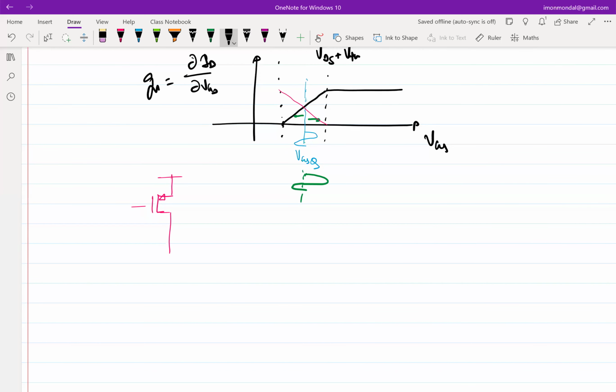And if I sum up the currents, which is normally pretty easily done, summing currents in analog circuits is probably one of the easiest things. You just connect the two terminals and ensure that they are not subtracted. You can both subtract or add, but fortunately, in the case of PMOS and NMOS, they both add up if you connect it like this. So if you do this, you should be able to get a fairly linear GM, provided their slopes are matching. Now, obviously, you'll have to bias it separately.